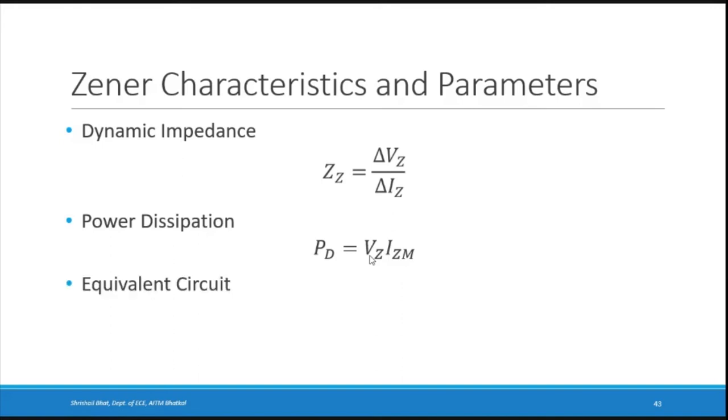Right? So if you consider the equivalent circuits, in the DC equivalent circuit in reverse bias, it will have a constant voltage. You can draw an equivalent of it with a DC voltage source, that is VZ, just like you drew for a forward biased diode, where it was VF, right? It will have a constant voltage drop across it in the forward direction. Here it is the reverse voltage of VZ.